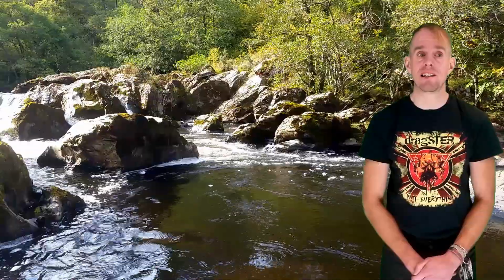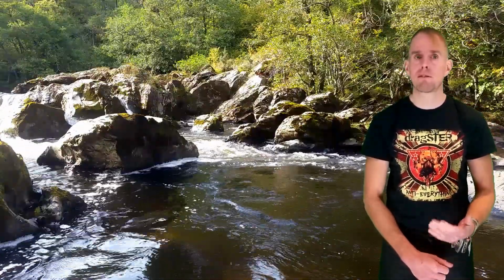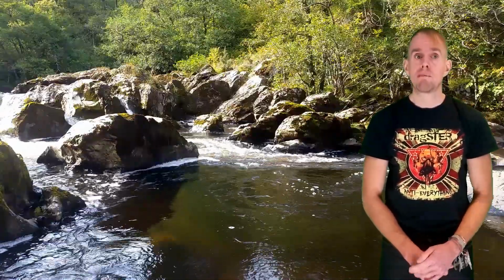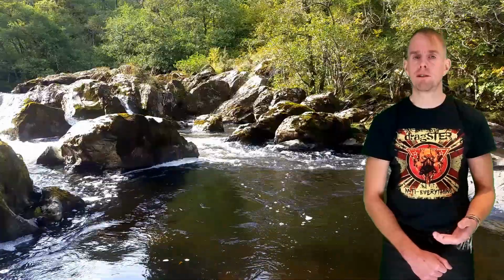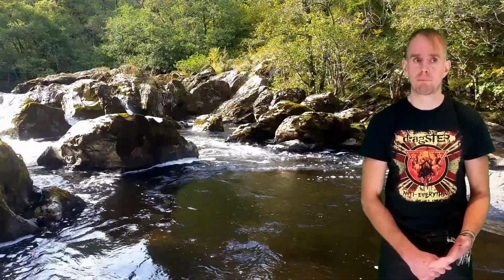Welcome back to Lecture 8. In this second part of Lecture 8, we're going to examine the mathematics of the Reynolds Averaged Navier Stokes, or RANS, approach to turbulence modelling. Remember that the RANS approach breaks down flow fields such as velocity and pressure into steady components and fluctuating components.